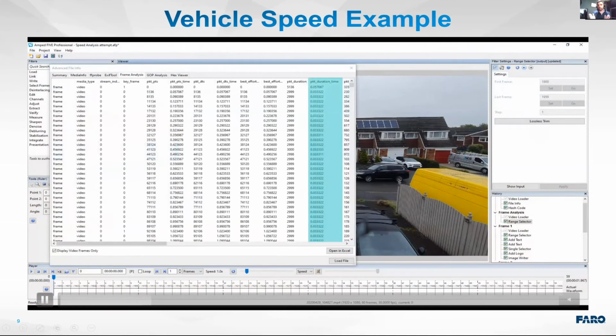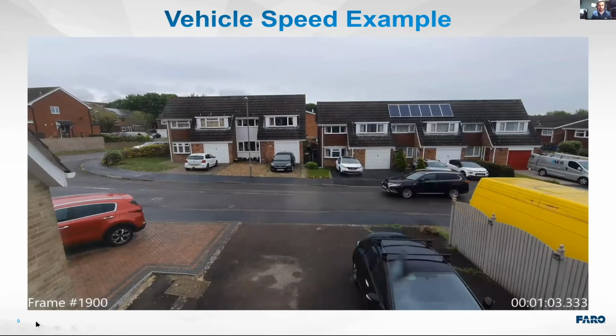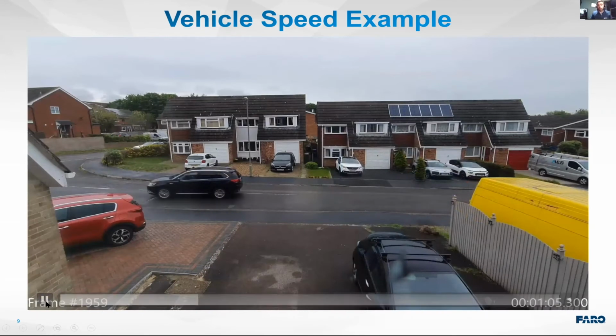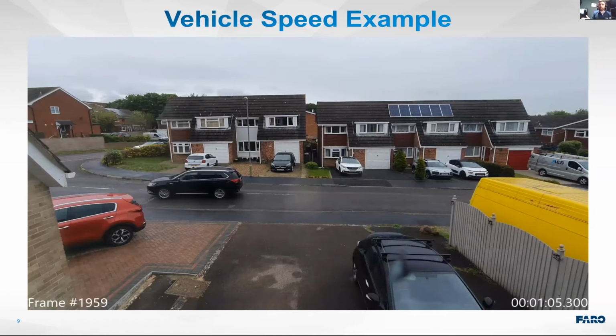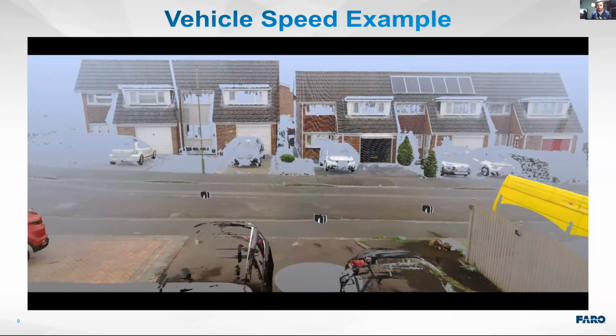So all I've done is recover 2 frames from the video footage. You can see here, frame 1900 and then frame 1959. What that means is I now have a perfect timing, providing I read the data correctly, because I know the frame rate, or I can read the variable frame rate of that video footage. I have a perfect timing between these 2 frames. So if I wanted to determine the speed of this vehicle, I now need to figure out the distance.